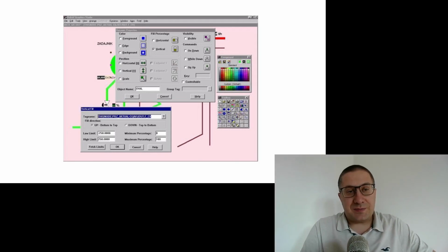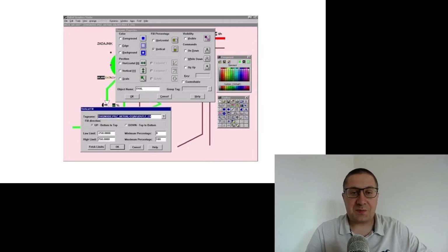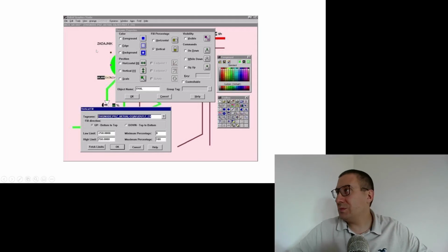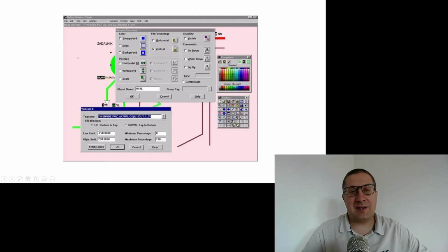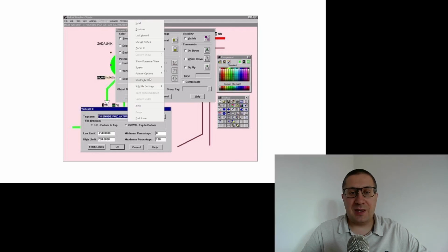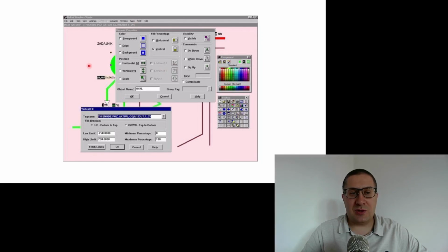All right. And here you can see how you can modify operator graphics. For instance, you can use some dedicated elements like bars, trends, some shapes. You can drag and drop some elements that present numbers, trends. You can add some logic to this. So, for example, if you would like to present the value of the steam temperature, you can drag and drop the element and put it on your graphic.